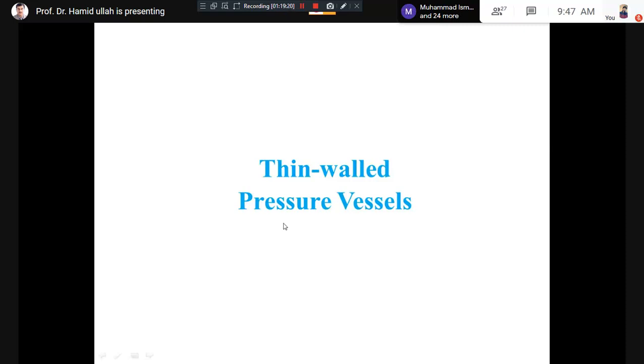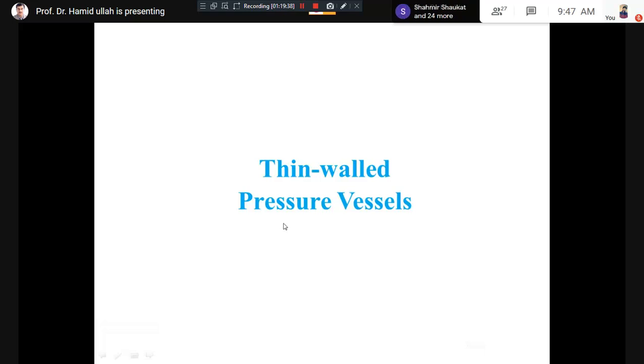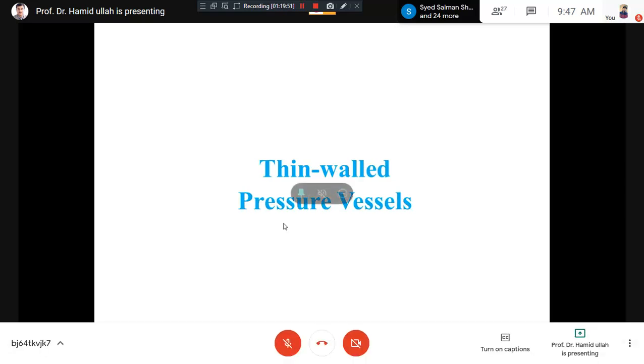It is the fluid under pressure, which is contained within the vessel. That pressurized fluid is loading the vessel because the gas under pressure is exerting pressure on the sides and walls of the vessel. And pressure equals force by area, a very common formula. Pressure equals force by area. So whenever there is pressure, there is a force, F by A.